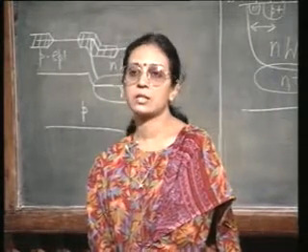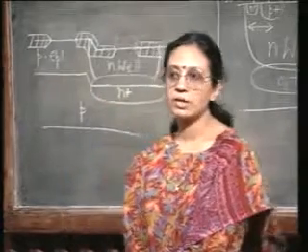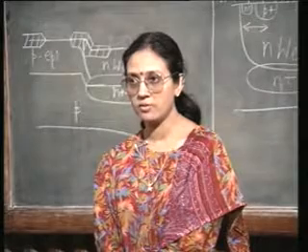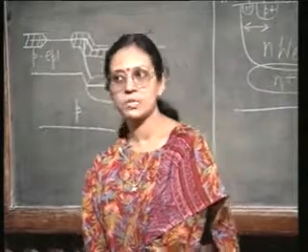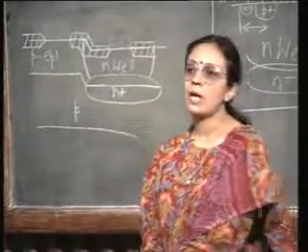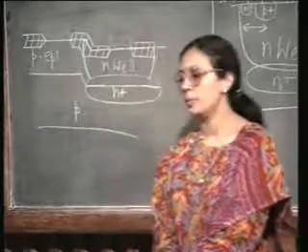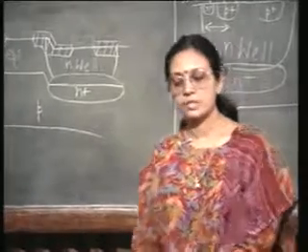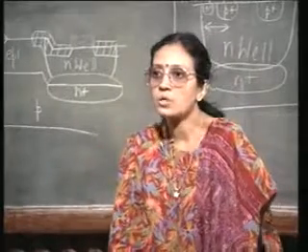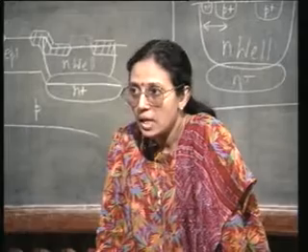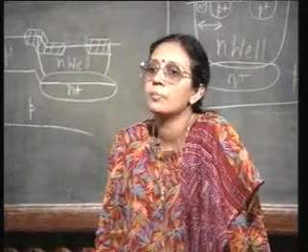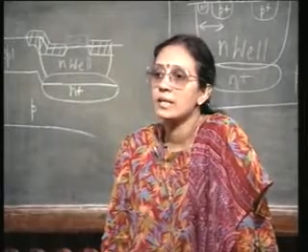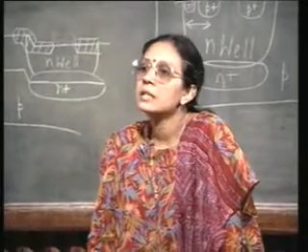Because as the circuit complexity increases, finally what puts the limit is how much power needs to be dissipated in a given area, right. So, there CMOS scores heavily. So, you have a combination of bipolar junction transistor and CMOS in a circuitry, and without sticking to one particular technology, but judiciously using a combination of both, you can achieve a performance enhancement with little extra cost.